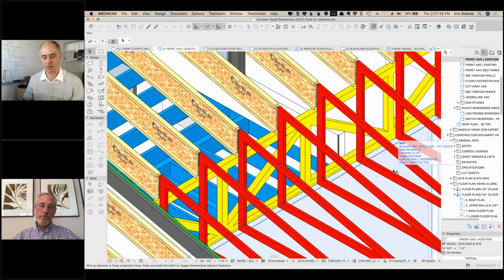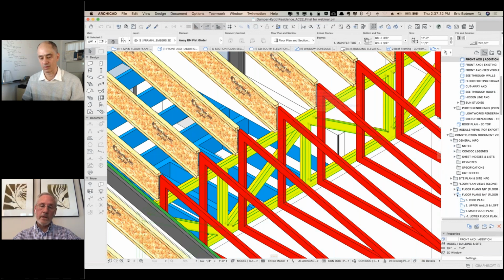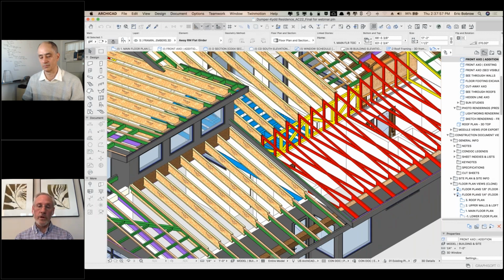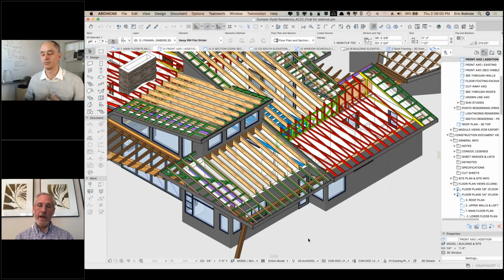This flat top girder, this particular detail here, had to be of sufficient height, obviously, to provide the strength, but it also supported the top of the sloped TJIs that form part of the vaulted ceiling on one side, and then the red trusses, which are just the common trusses, on the other side, which have a flat ceiling on the underside. I wouldn't have known whether that could actually be done until I sent it to the truss manufacturer, and then I get his design drawings back, and then I make some adjustments if I have to.